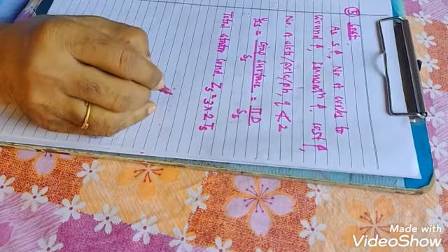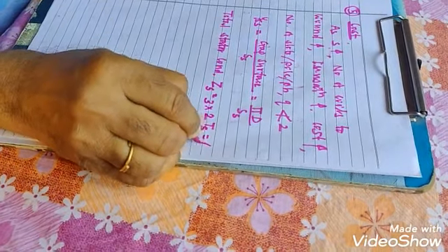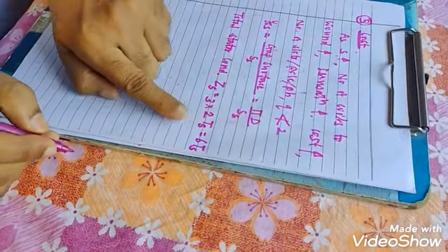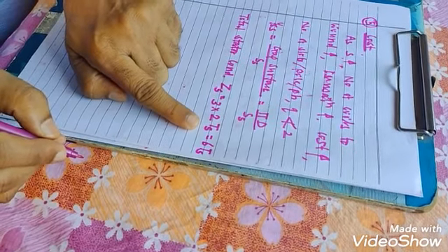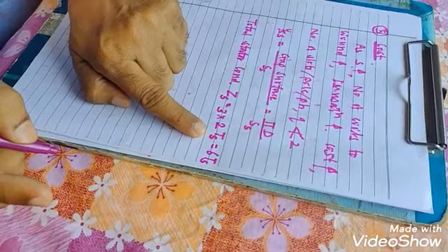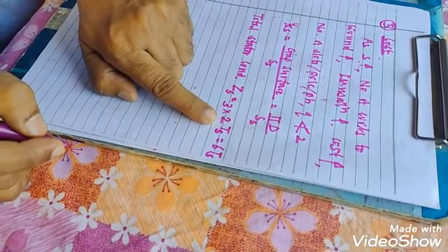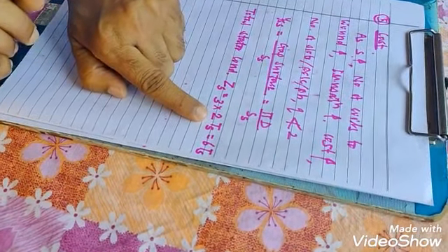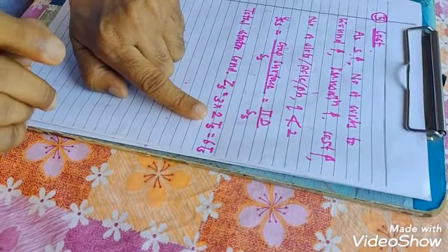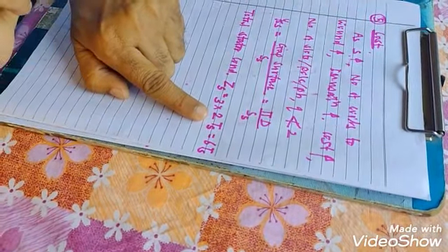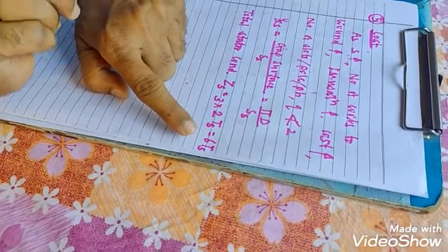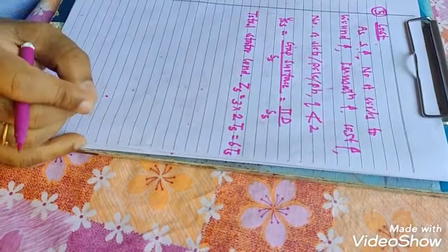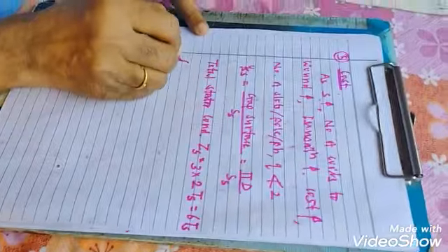So this is the total stator conductors and is equal to 6 TS. So from the above calculation we have stator turns per phase TS. TS is multiplied by 2, so we get stator conductors per phase. Stator conductors per phase is multiplied by the number of phases 3, so we get total stator conductors, equal to 6 TS. From this, conductors per slot is calculated.